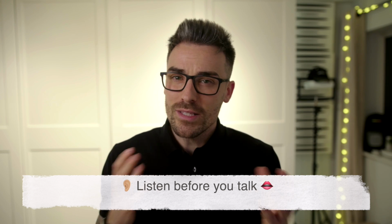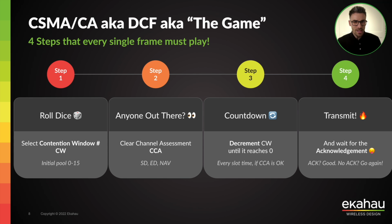So what is that threshold that these devices will be listening out for if they can hear another device on that same channel? Typically this is at around minus 85 dBm. So why do we say that this threshold is around minus 85 dBm?